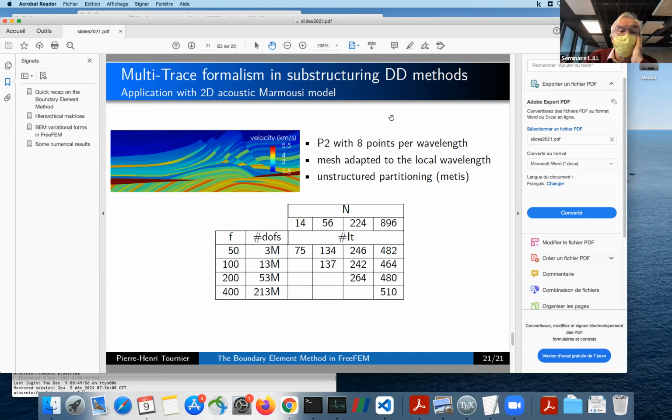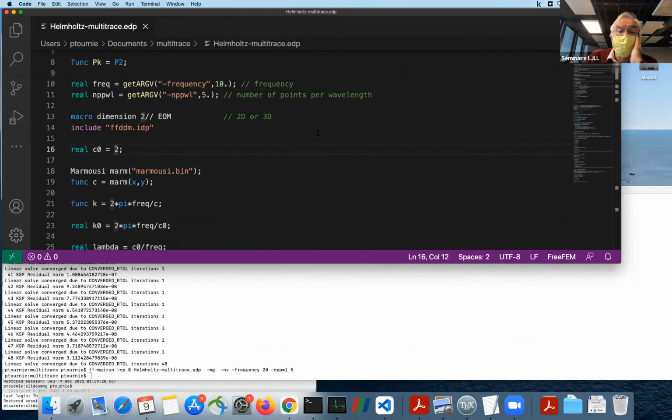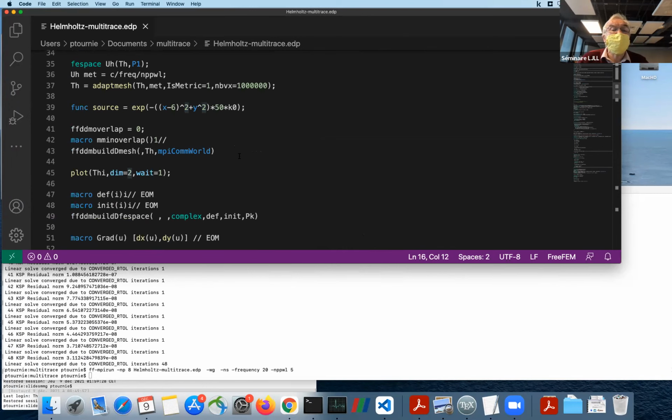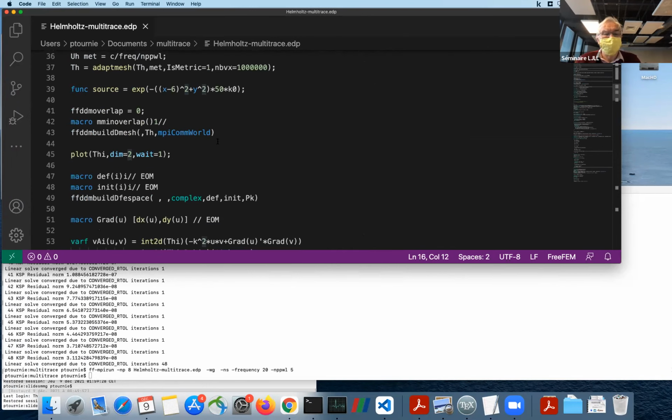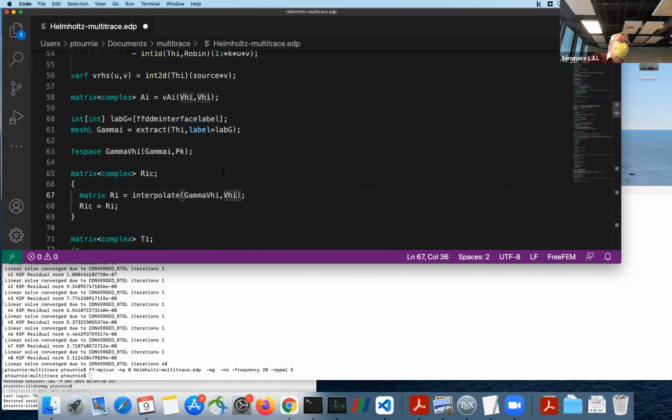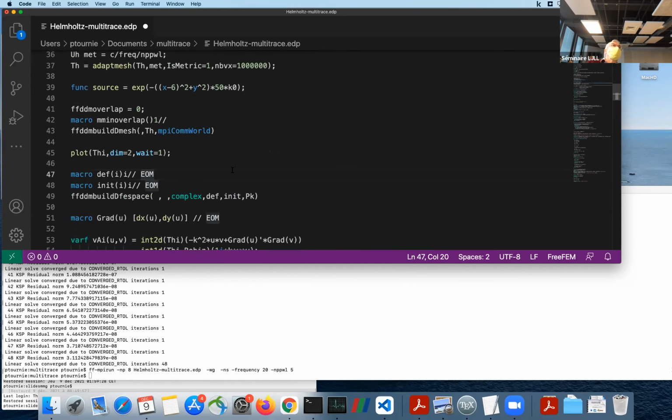So in your script, I have two questions in particular. At one point, you have FreeFem macros where there are just commas and no parameters, in the mesh. Yes, I didn't go into the details, but usually you have a user-defined prefix in order to have multiple decompositions or multiple distributed finite element spaces in the same script. But here, since we only do one thing, you can also have an empty prefix. That way, the local mesh, for example, is called Th, which normally would be prefixed with my prefix. But since it's empty, it was for simplification, but actually maybe it leads to more confusion.